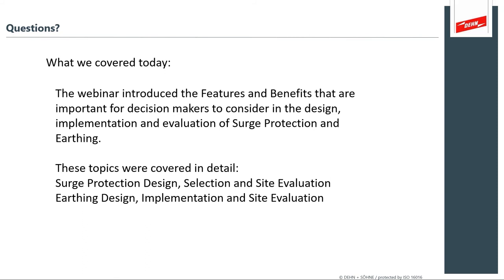Yes, I'm sorry, Mark. I thought you were done with that question. How do you test newly built earth pits with a clamp tester when the pits are still isolated from the system? I'm not sure I understand that question. Can you repeat that again? He's asking, how do you test newly built earth pits with a clamp tester when the pits are isolated from the systems? If I may, Mark, remember we use a clamp tester to measure if there's a conductive loop in the system. In other words, everything is properly connected together.